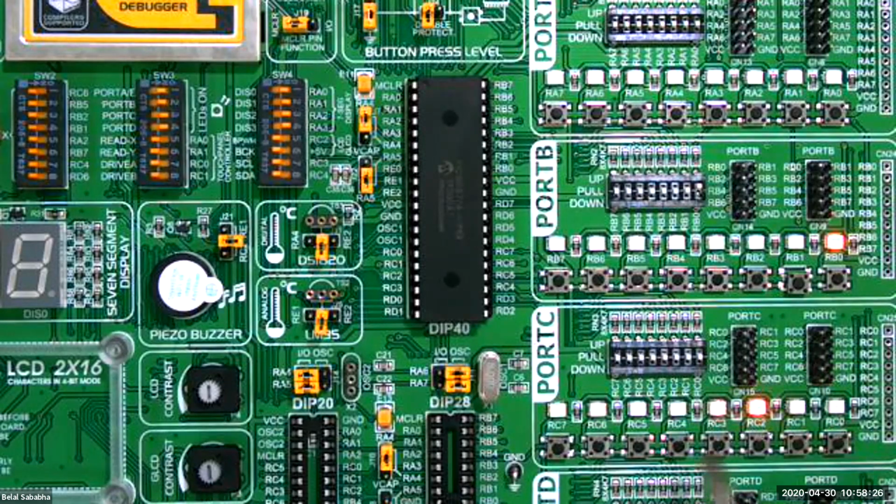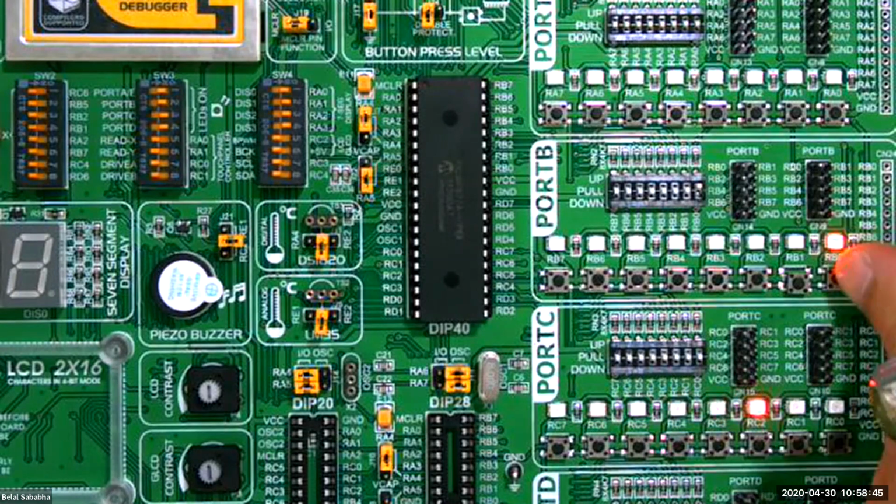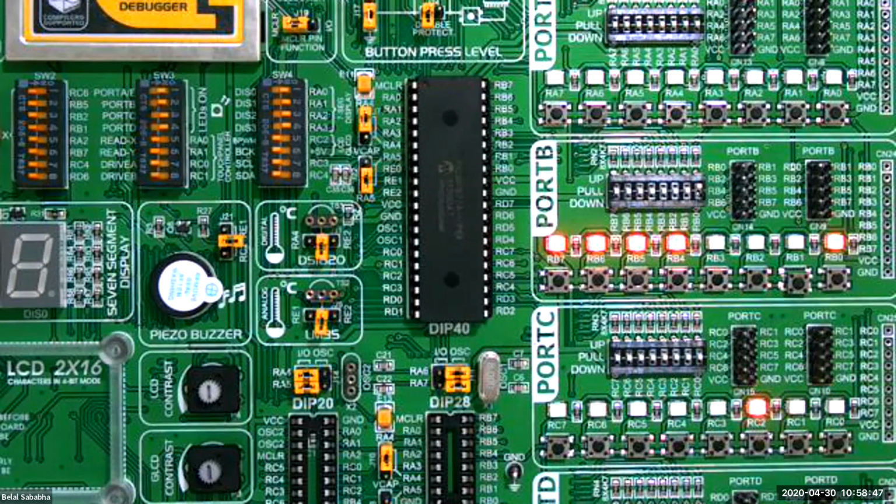See, we did not reset. The problem we had with the shift counter was that we did not reset it. We assigned the shift counter a 14 every time, so it stopped the first if condition. See, the shifting is very accurate, 500 milliseconds. Whenever we do an external interrupt, look, we did not stop shifting.